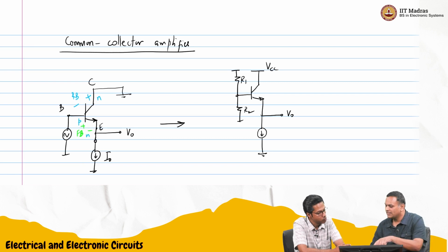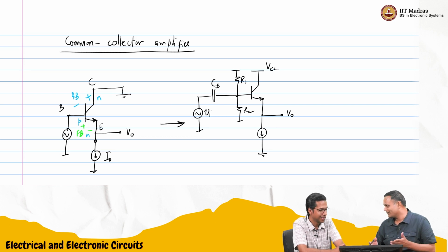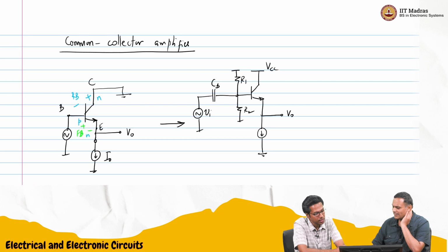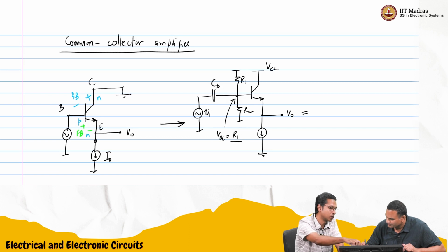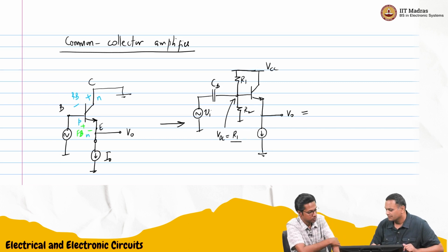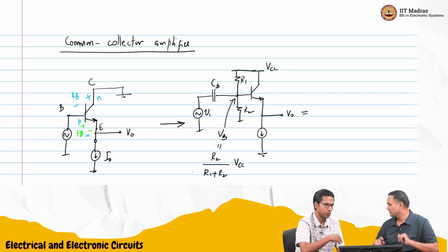So this will make sure that there is some DC voltage, and now we can couple the signal through the capacitor. Now I'm sure the students understand this quite well. They have seen this like the third or fourth time. And we also know the DC voltage here, if the top is connected to VCC, the same VCC, so this voltage is VB. So this is the base voltage.